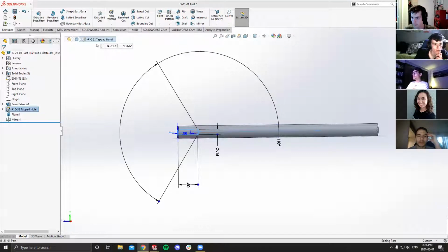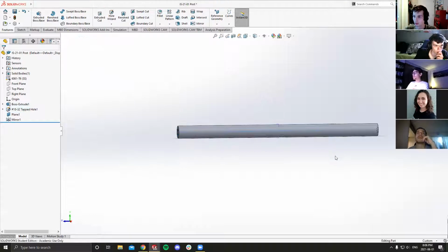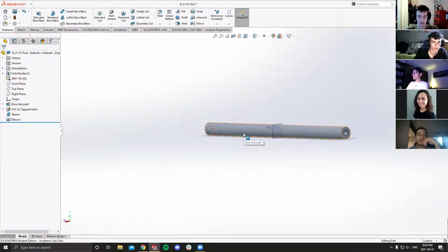So we're almost done. We're finalizing the part. We already selected the material 6061-T6, so that is great. You can see it's in bold. Every part needs a material, and we already talked about a distinguishable name, which we already have. That's very important for mass calculations because every material profile has a density within Solidworks.